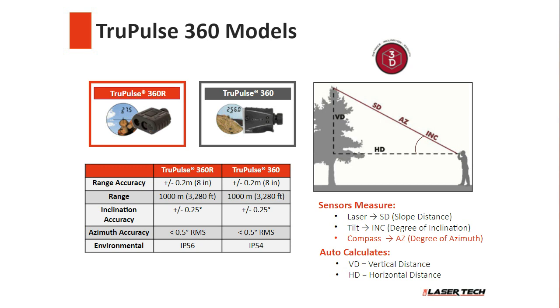One thing to note is the azimuth accuracy. That's our biggest thing I talked about: we have no tilt or roll limitations with this. And so we're down to 1/2 degree. That's really going to come into play when Steve talks about some position accuracies of what we're looking at. So now I'm going to turn it over to Steve, and he's going to talk more about ways you incorporate laser rangefinders into different data collection workflows.